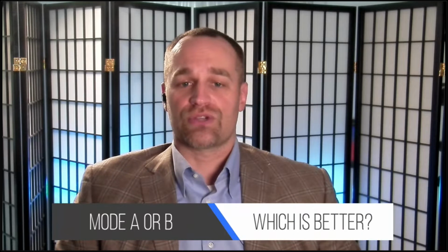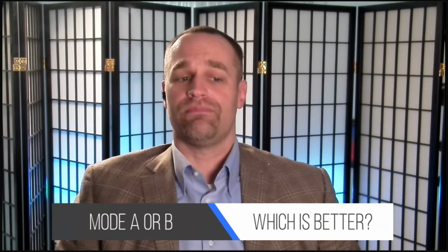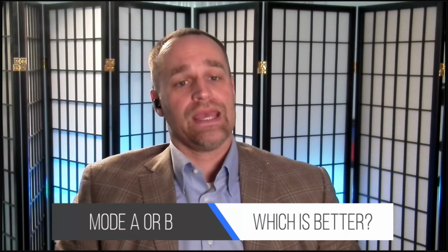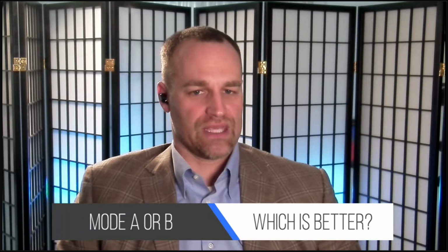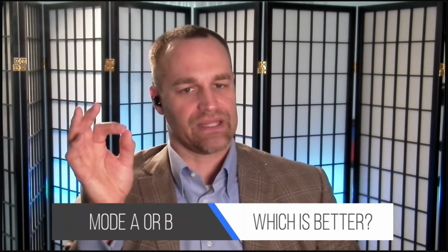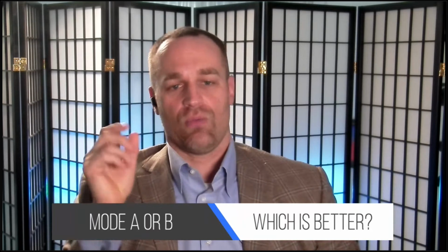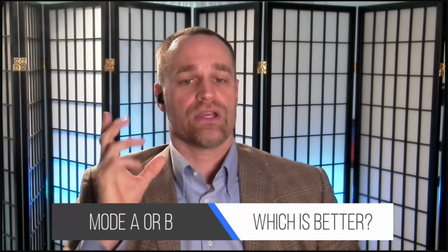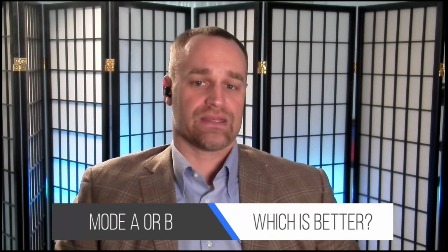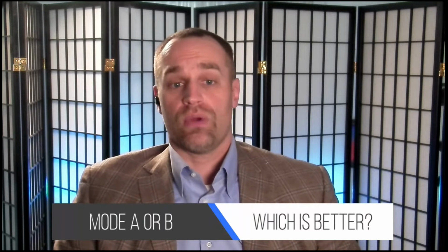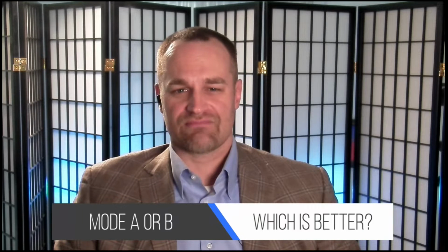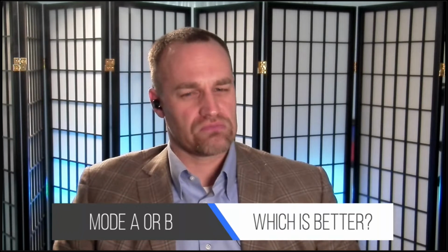Does it matter which mode you use in the other? It matters when powering a 24 volt passive PoE device. Typically MikroTik, Ubiquiti, when they do that 24 volt power, you do need mode B because that's the way they've built them. When powering a 48 volt device, it shouldn't really matter.